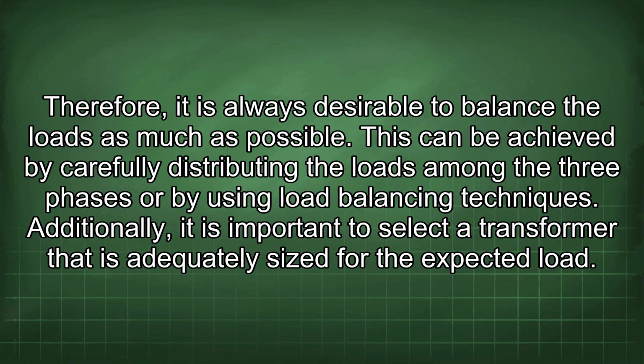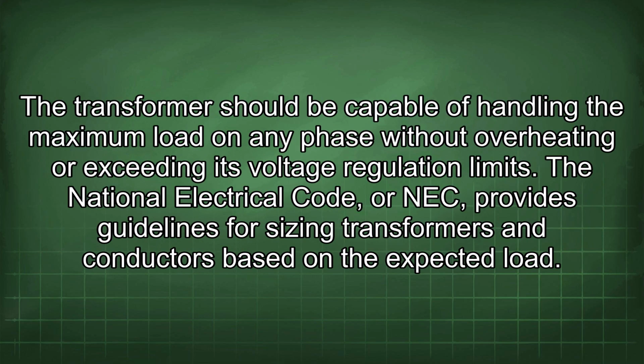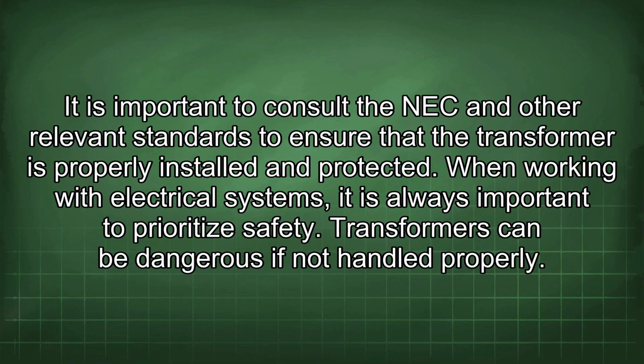Additionally, it is important to select a transformer that is adequately sized for the expected load. The transformer should be capable of handling the maximum load on any phase without overheating or exceeding its voltage regulation limits. The National Electrical Code, or NEC, provides guidelines for sizing transformers and conductors based on the expected load. It is important to consult the NEC and other relevant standards to ensure that the transformer is properly installed and protected.